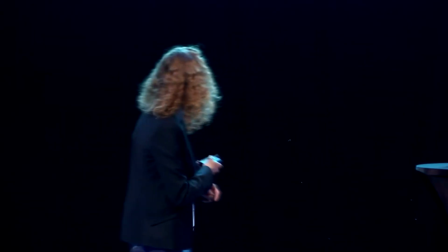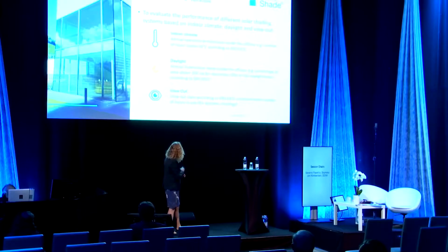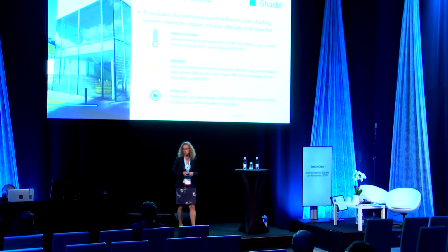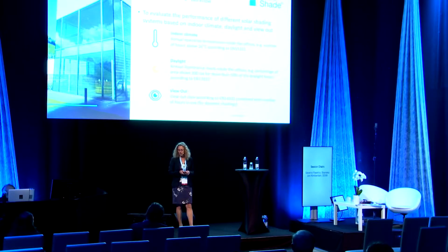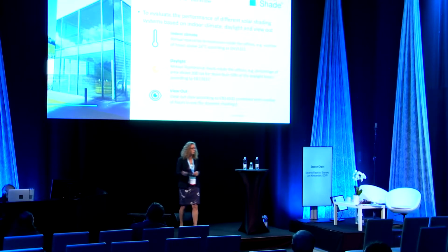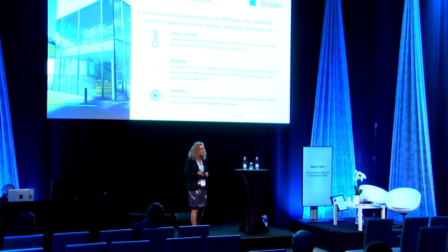And then for the view out, we look at the view out class according to the standard EN 14501, which is a standard that classifies different aspects of solar shadings. And then we combine this with the number of hours that the shading is actually activated.